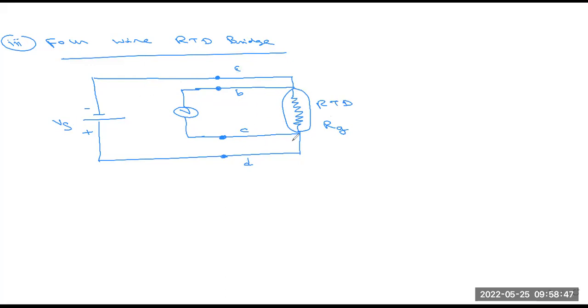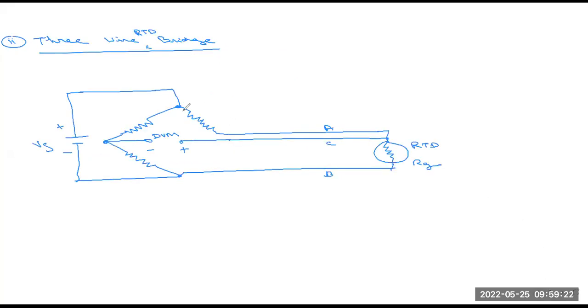It is also connected from here. So the four-wire RTD is basically used for a large, huge range of temperature, when the temperature changes continuously. At this time we have to use this type of four-wire RTD device. And basically in our industrial purposes, we use these three-wire RTD type of devices.